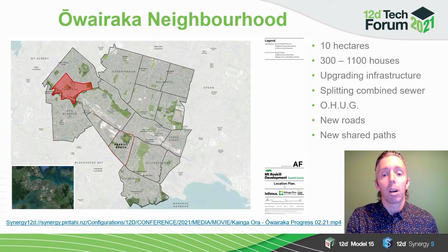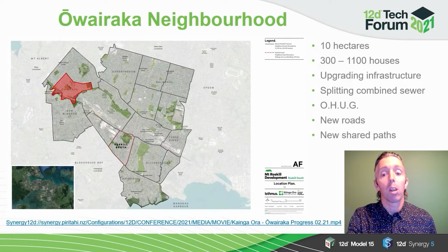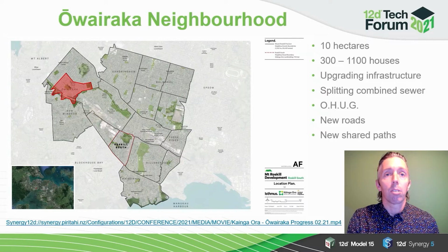Stormwater-wise, we have provided hydrological mitigation by means of treatment and retention to comply with local standards. We have constructed 4.5 kilometres of stormwater pipes. This is for pipe sizes between 200 millimetres to 1650 diameter throughout the development.